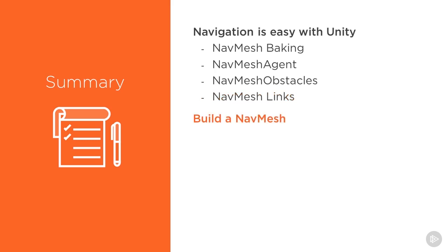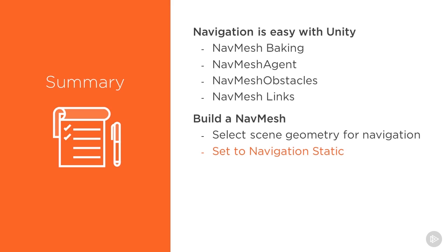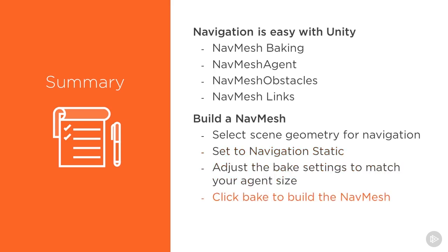We also built a nav mesh. We selected scene geometry for navigation, we set it to navigation static, we adjusted the bake settings to match our agent size, and we clicked bake to build the nav mesh.